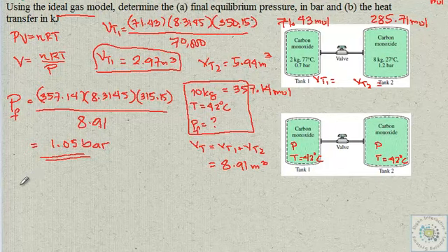Now we always refer to, this is a closed system, right? If we think of the whole tank, the two tanks, as our system, it's a closed system. Nothing leaks to the surrounding. So in this case, we can use the equation delta U is equal to Q plus W, right? Since there's no work, because there's no expansion work, no shaft, no electrical power input, W will be 0 because the tank is rigid, so it's not doing work on the surrounding. Therefore, Q will just be equal to delta U.